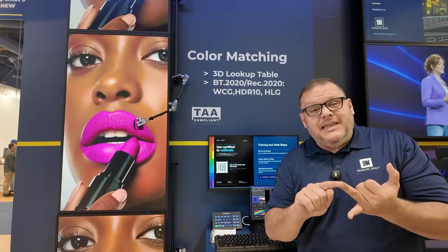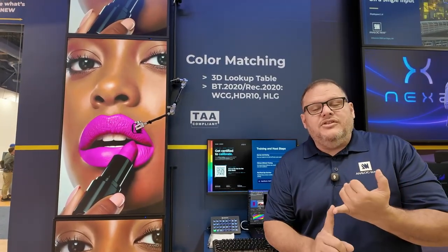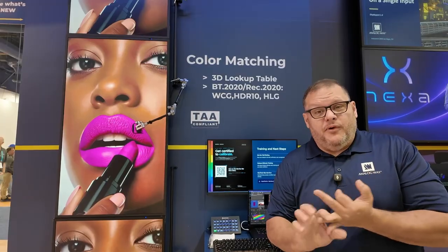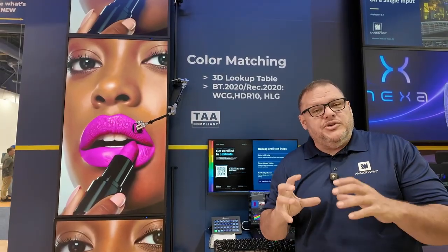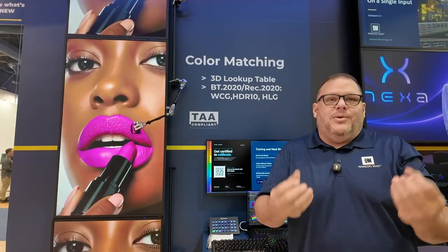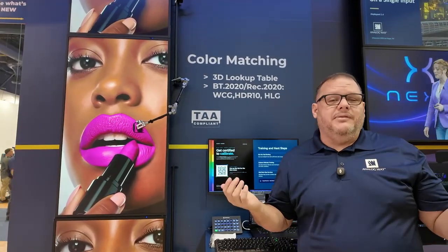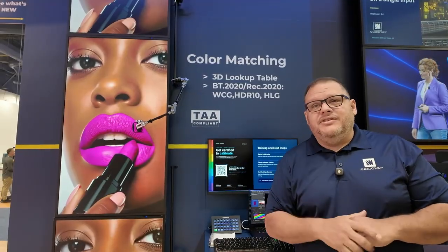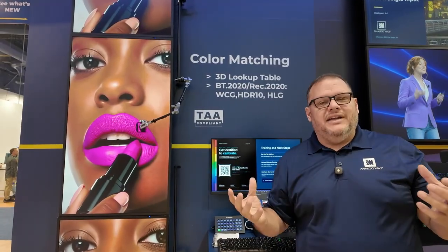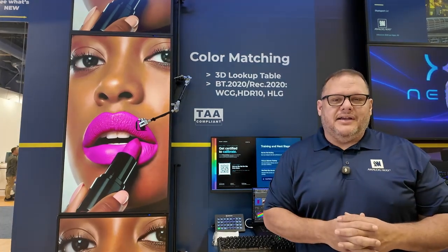We can do LUTs from DP to HDMI to SDI on both sides, connectors. The other thing we can do is at 12-bit, 444, so no banding. So it's huge. I mean, the amount of processing power that's in here is tremendous, and I don't work for Analog Way, but I'm a real advocate because I've used these tools, and I've been in the business of 35 years, and I haven't seen something that's this industry changing in a long time, and it's kind of a kept secret until hopefully you guys see this and come ask us about it.